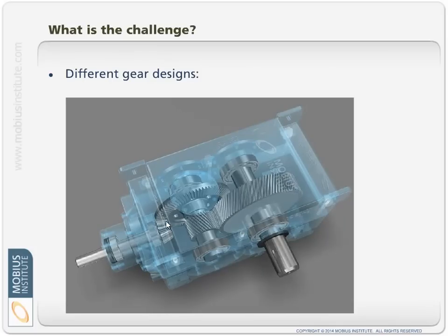In this case, we've got a bevel gear which creates sort of more axial vibration, and a spur gear which creates more radial vibration, and we've got certain measurement points that we can use, so we just need to be sensitive to what the forces are like, and therefore you may, in this instance, take an axial reading as well as a radial reading. But of course you've got to look at what mounting points you have available, how thick is the metal, are you going to be dealing with resonance.